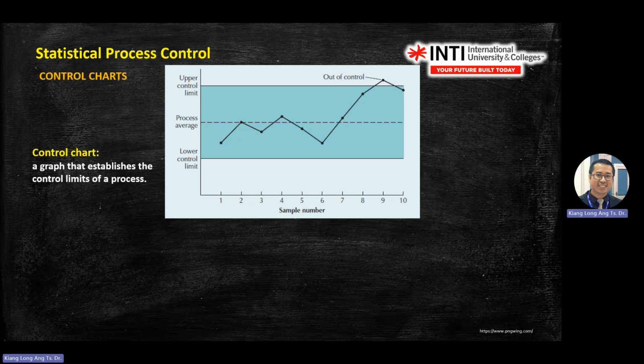Here the machine might already start to wear and tear, start to go out of control. You need to adjust it back, maybe because of the vibration. The way you cut the things already starts to run away. Or maybe the operator starts to fatigue. It means he has worked for long hours and wants to fall asleep. So when he does the work, the quality starts to move towards the upper limit. Okay.